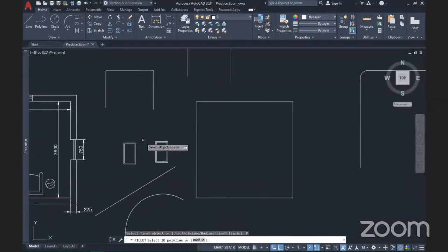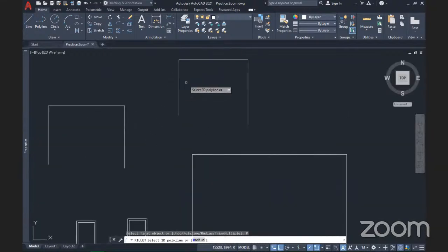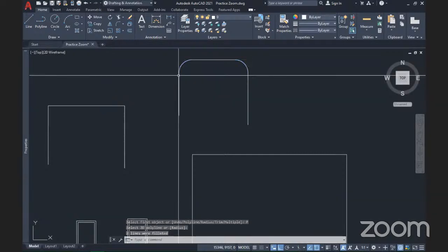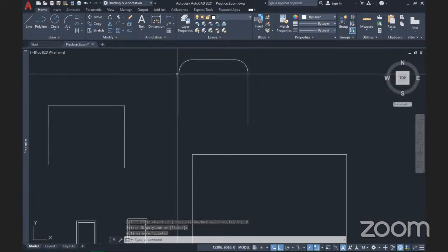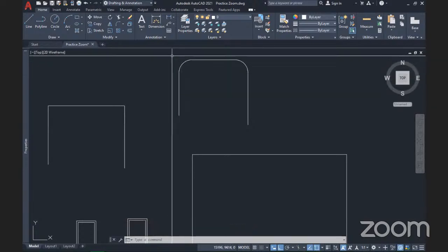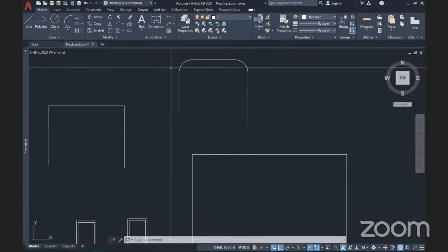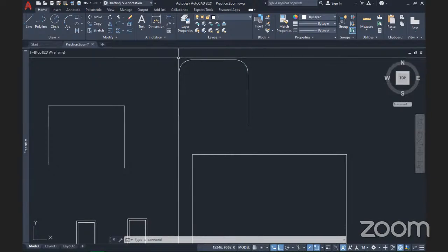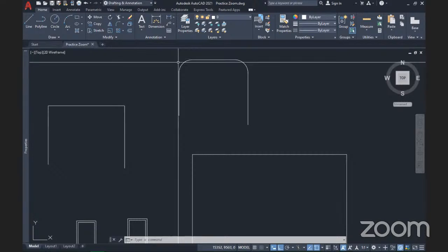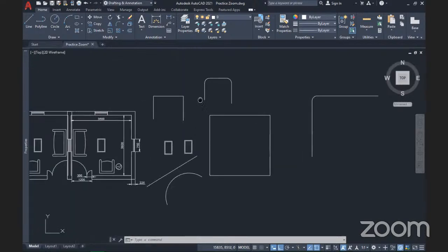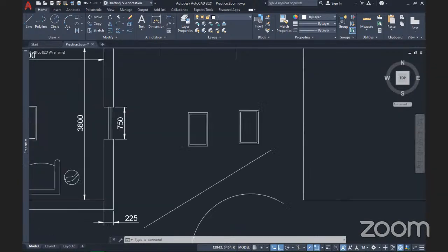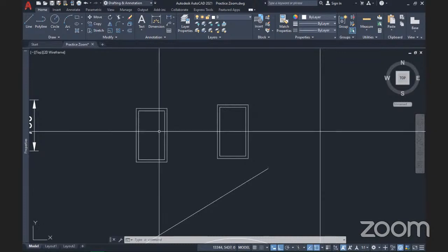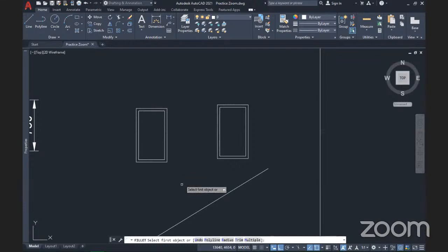Now, since we've inputted 300 as a radius, if we click on this polyline, like so, it has already filleted the polyline. So all the perpendicular areas, where two lines met, were all filleted and it created this very smooth curve, like so. So that we will have to effect that change to the table to make it look nice. How do we do that? We go to the Fillet command and change the radius because that 300 radius was too big.